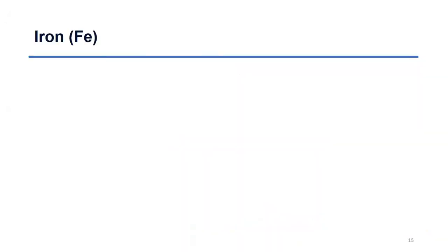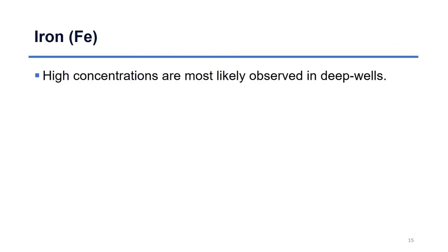So the first thing that I highly recommend is we start by suspecting iron is a problem. So we want to understand, okay, if I have a well, iron might be a problem. If I don't have wells, it's very unlikely that iron is a problem. The reason is you can roughly classify water sources by the type of problems you can find. And iron issues are mostly a problem in deep wells, right? You can imagine if you have a very deep well and there's weathering of minerals in the surface surrounding your well, that's accumulating in your well. So that's part of the reason.